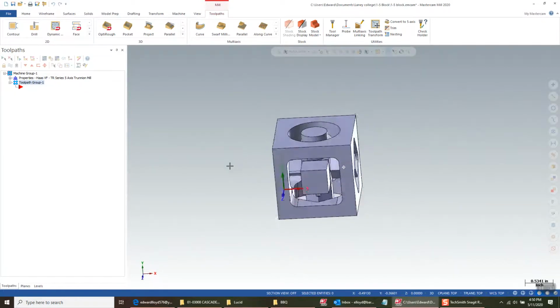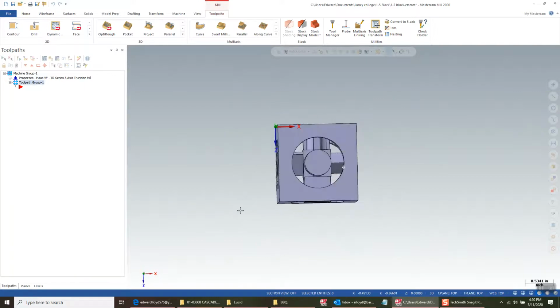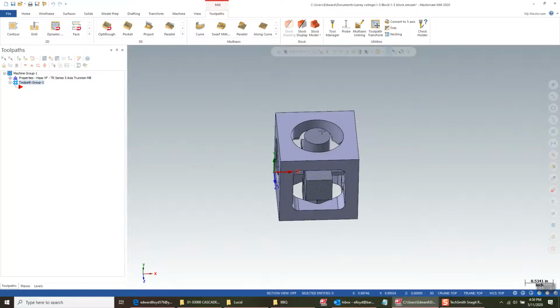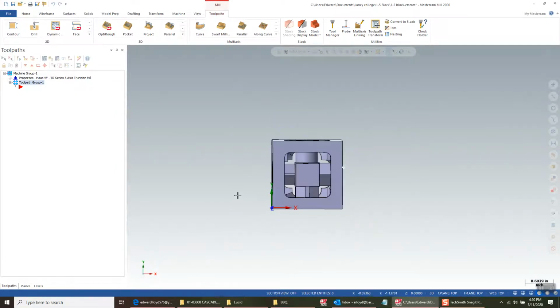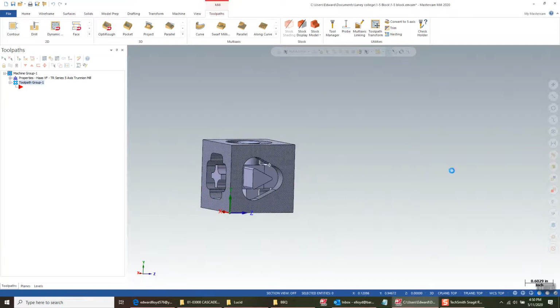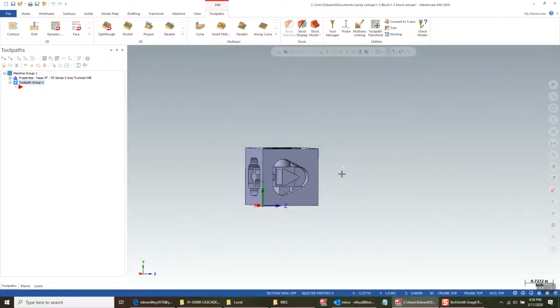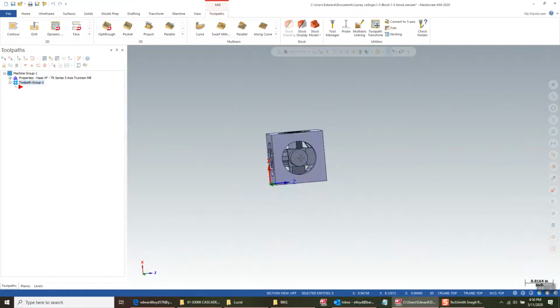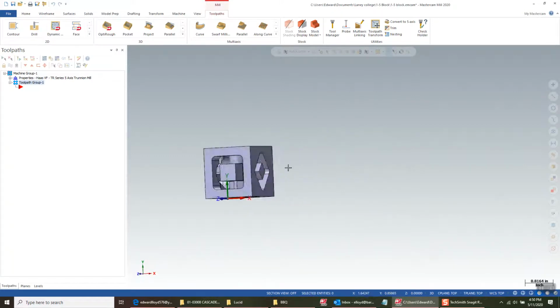Just on the horizontal, whichever faces your top face, you can't machine that one, right? So on the horizontal, if this circular feature face was the top facing up, then we'd only be able to get to the sides for machining those shapes. Whereas in the fifth axis, we can do this as well as all the side faces.